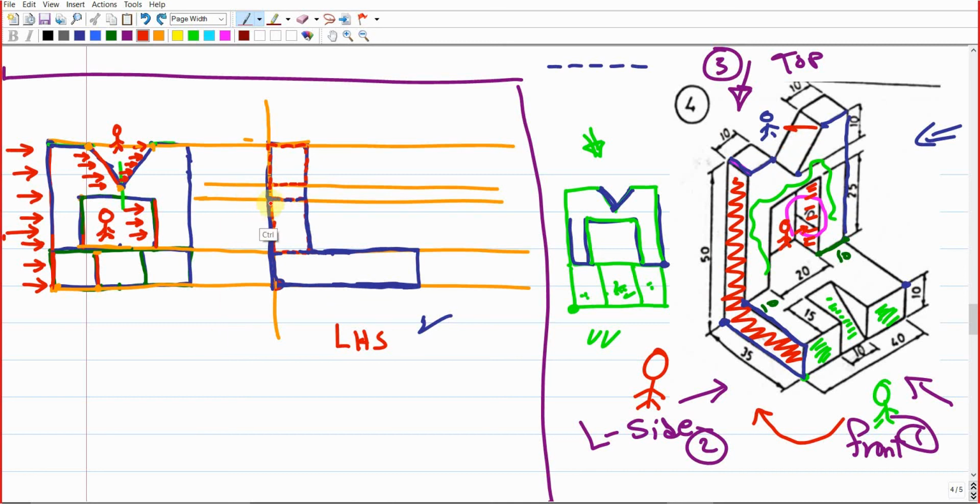But if we try to draw a dash line over solid line, it will be seen as a solid line. So dash over solid will be solid. Then we're going to have a dash line, then a solid line. Then there is a dash line over solid, which will be seen solid. So we're just going to end up with 3 dash lines here, 1, 2, and 3. So we got the third feature.